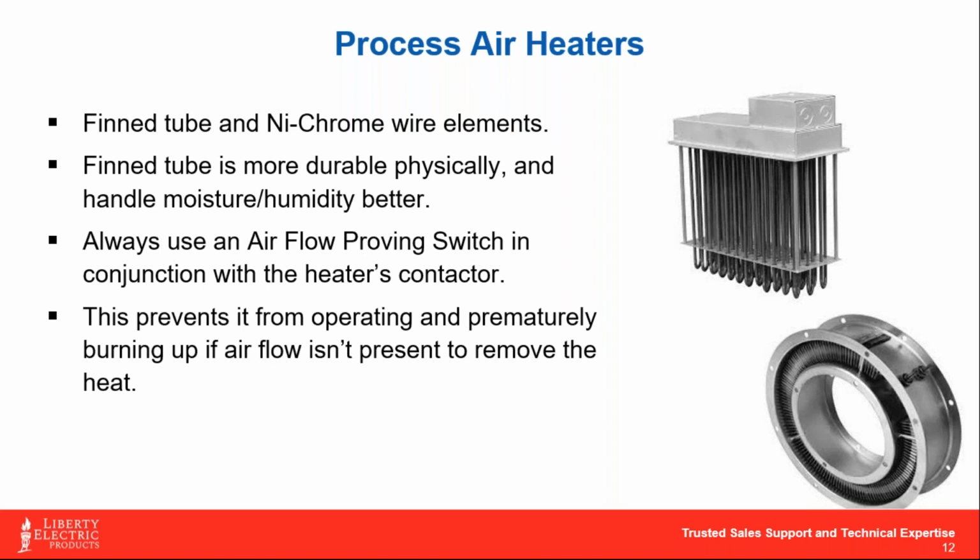To give you a quick difference between the two, a fin tube element is something like you might see in a baseboard heater, okay? You'll have a tubular element with a bunch of aluminum fins or copper fins or whatever that material is, steel. If it has to be anti-corrosive, it's stainless steel. What it does is help the transference of heat. As that element is warming up, it's transferring heat to those fins, which helps take up more surface area within that heater and pass more air through it. These are usually very robust. They handle moisture a lot better than the open coil version does.